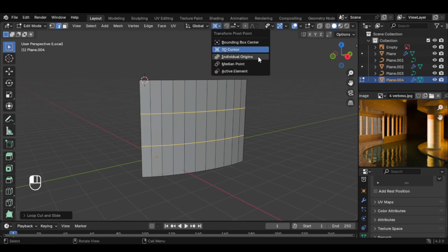And let's select this by pressing Alt and click it and press G and Z. We make this a bit higher. We can make this a bit higher, like G and Z, to about here. And what we can do now is go 3 to face select mode. And let's select these faces by pressing C. Let's press I and I again, so you can change it. And let's make it like this, and you can hold Shift so you have more control, and press X to delete these faces here.